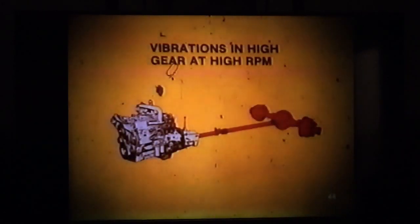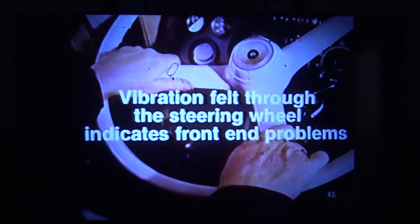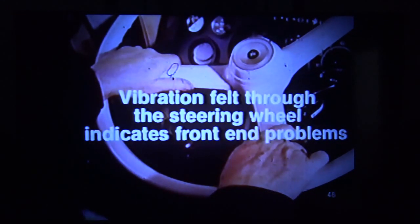In cases where the vibration is detected only in the higher gear selections at higher engine RPMs, it is unlikely that the problem is generated within the geared component. This is only if the complaint was not noticeable at low speeds. Should loading, acceleration, or deceleration have an effect on the vibration, the cause is most likely in the propeller shafts and associated parts.